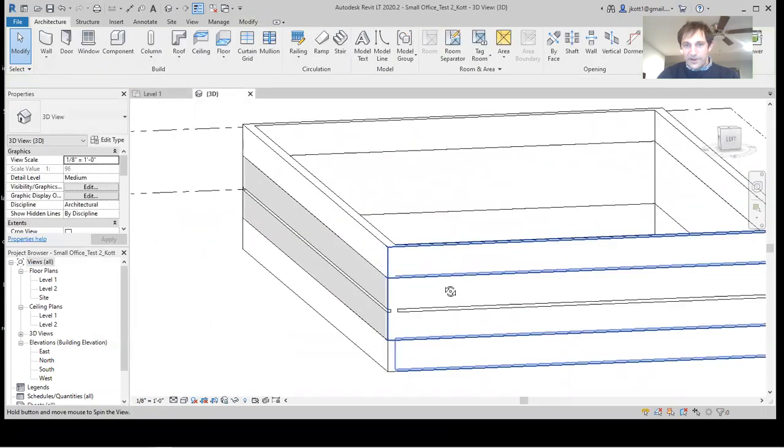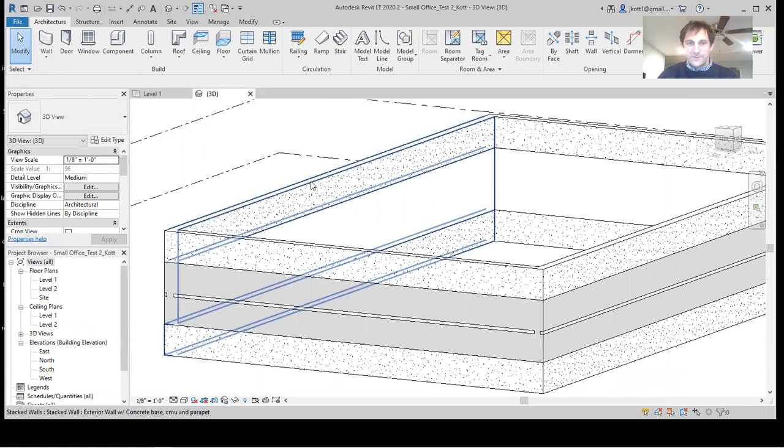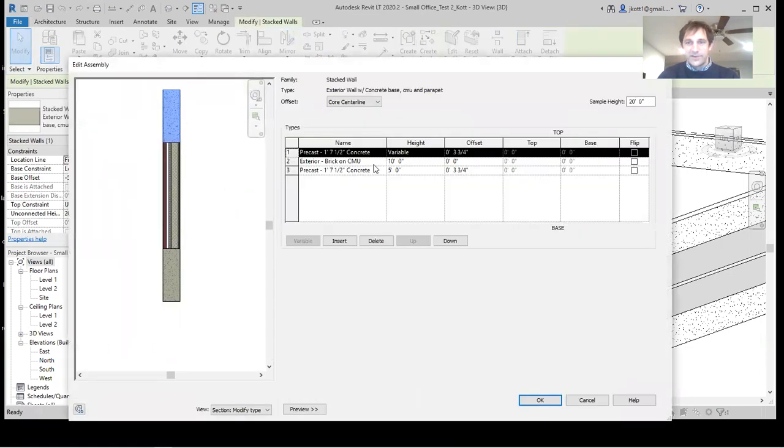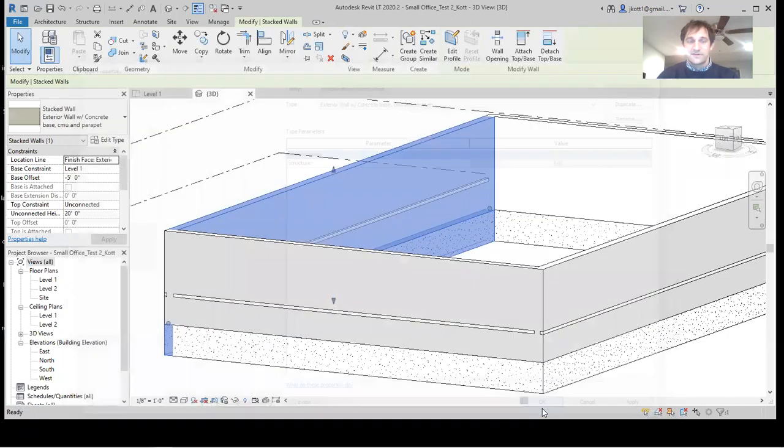And that's kind of what the prompt asks us to do. But now we do have to make some adjustments to our wall. We want to adjust the height of the brick so that rather than the exterior brick being a 10, we want the whole building itself to be a 10. So let's set it to 15, right? Press OK, press OK.